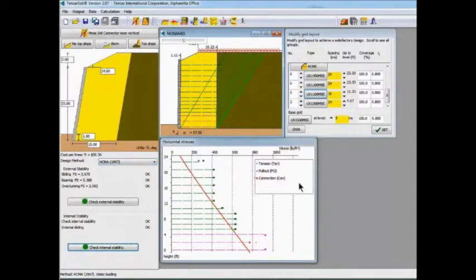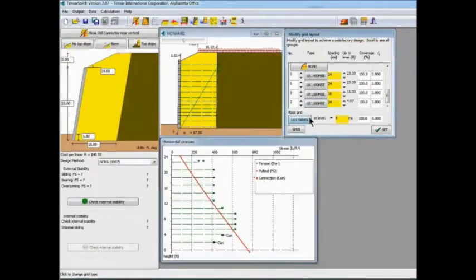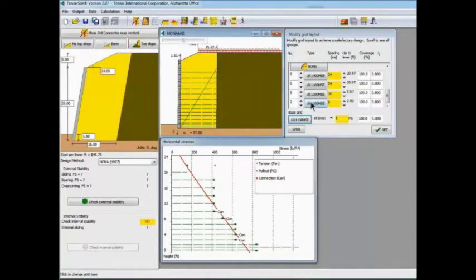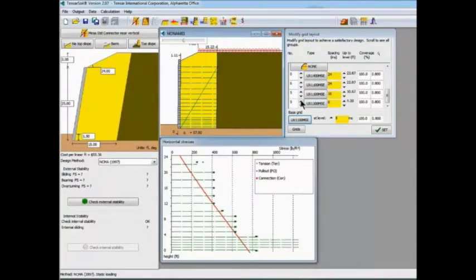Alternatively, you may look at this and say, I'd like to do this all with one type of Geogrid. What if we just changed it all to UX 1100? Could we optimize it with different spacing? So let's go ahead and do that. If we drop this down to 8 inches, now the wall passes. So all with our weakest type of Geogrid at different spacing, we are at $58.57 per linear foot.